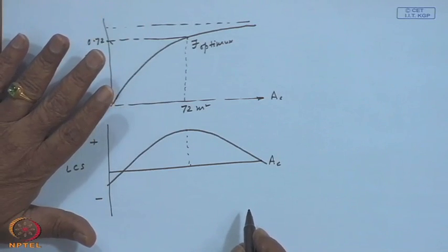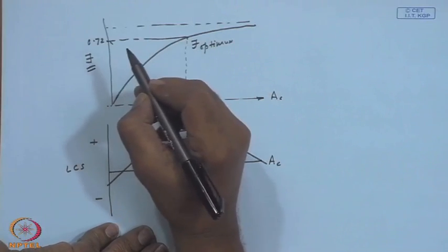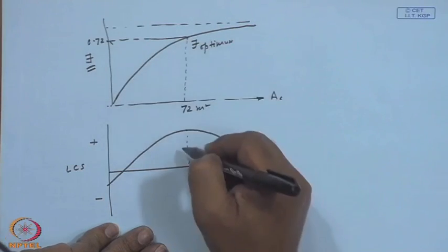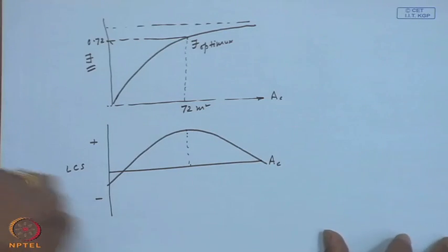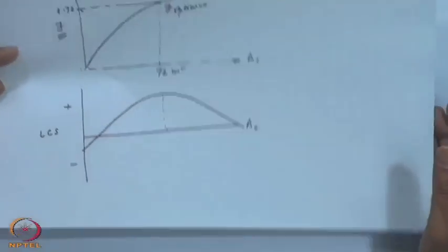One thing this is propagating is, you do not need to aim for a 100% solar load fraction, but you aim to maximize life cycle savings, because initially some subconscious feeling is to show that solar can do everything, but I think wisdom prevails, and the objective is that it is not a substitute. You do not want to replace one energy source with another energy source. You would like to utilize where it is best. Solar may be best in certain applications, auxiliary heating using coal may be better at some other place.